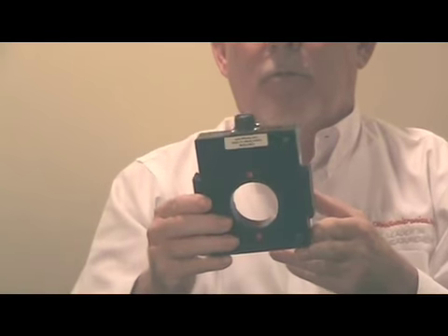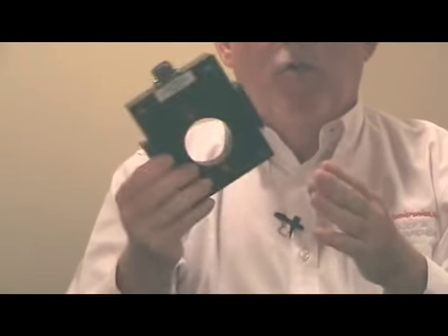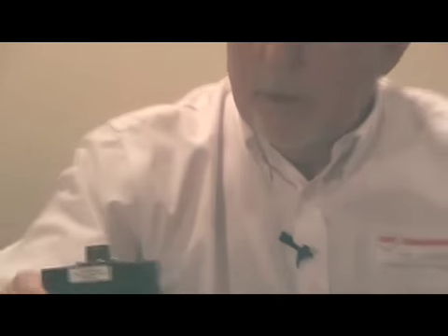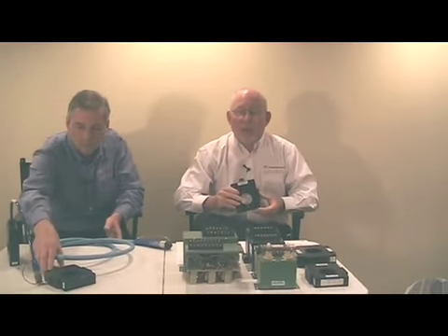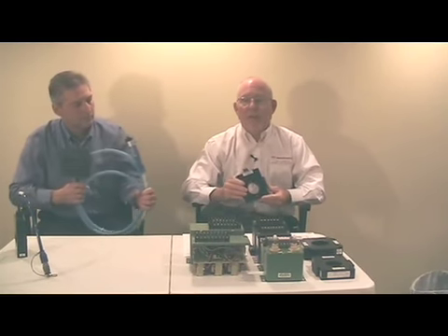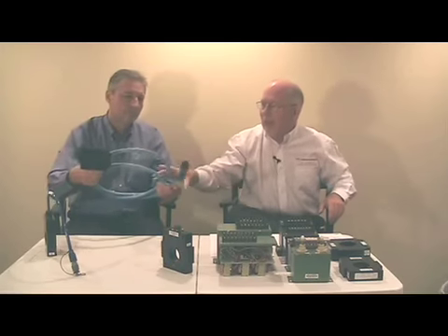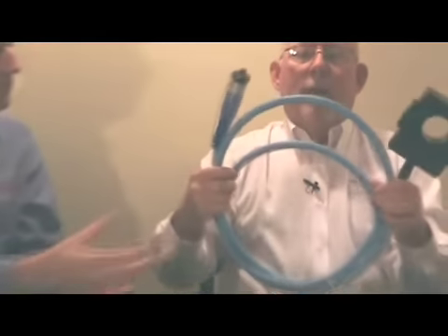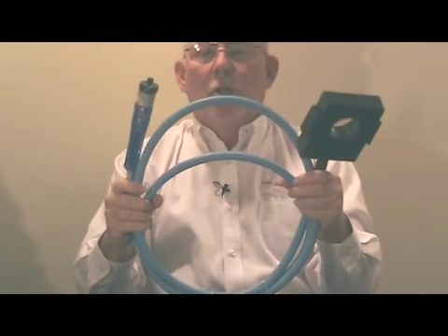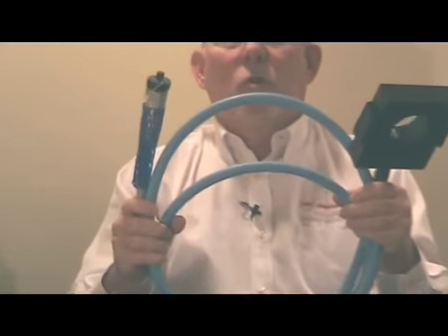What I wanted to do today is give you some examples of what a typical Y number request from a customer might be. This happens to be a 2,000 amp Hall effect current sensor. It's standard in our catalog, and you can see that the standard model is designed with a connector. We have some customers who, for safety reasons in this particular example, have a specific type of cabling and a specific type of connector that they use for electrical products on an offshore drilling rig.